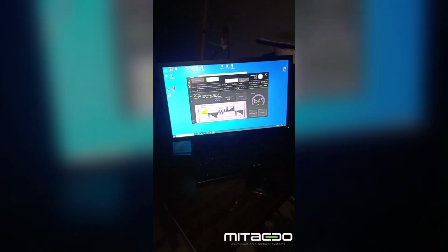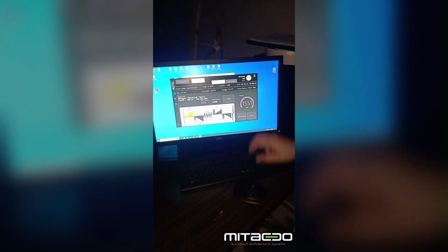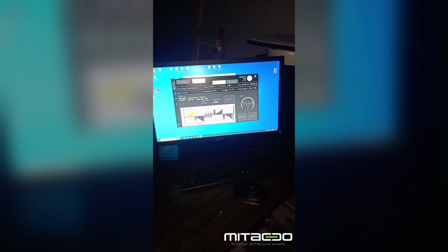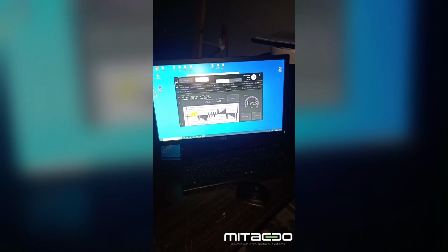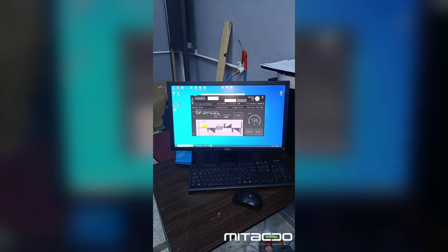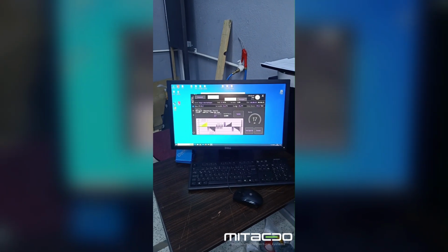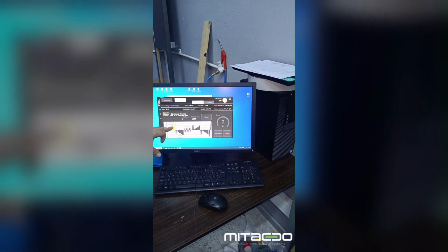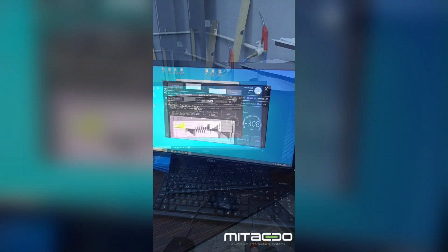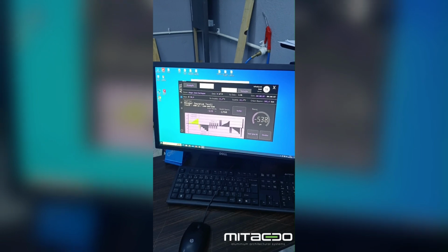Now we are coming to 1,600 pascals. We will wait 15 seconds. When we see 1,600 pascal, it will decrease gradually. Now it will drop back to 0. It will drop to 0 and wait. It will count. We passed 15 seconds. It will count again after it reaches 0. Now the negative test has started.